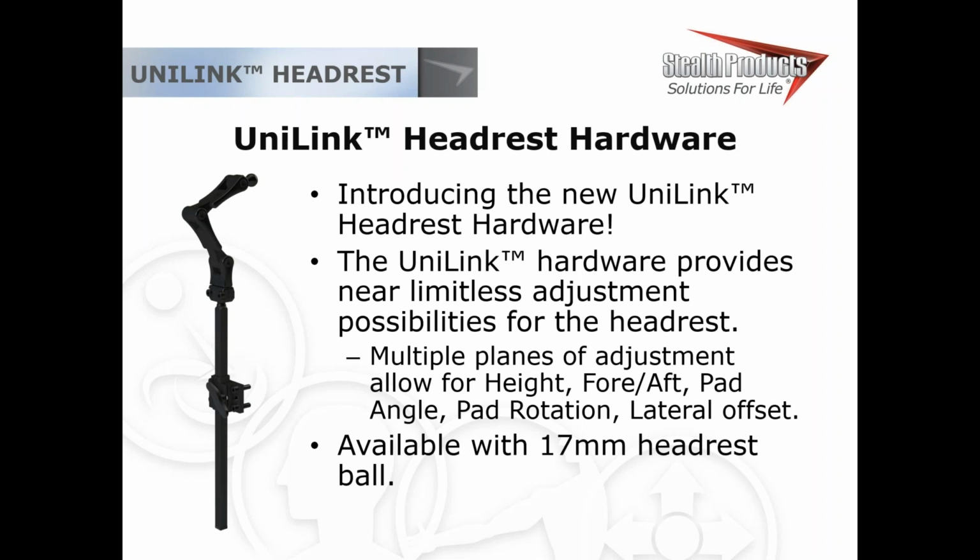What it's going to do is give us a near limitless adjustment possibility, same as TWB, just does it a little cleaner and simpler. So multiple planes of adjustment, you've got multiple ways to adjust height, you've got fore and aft adjustments, you've got pad angles, pad rotations, lateral offsets, you've got a couple balls to play with, so you've got a lot of ways to go here. And it's all going to be transitioning over to a 17mm ball. Standardizing that size as well is kind of important, so no more 1-inch ball kit.